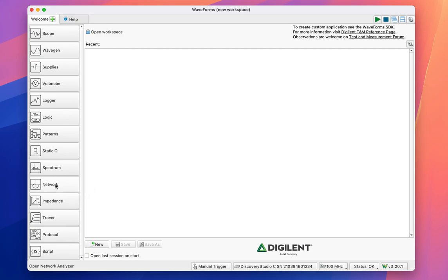with specific values. The ones that I'm using are, for the resistor, 300 ohms, and for the capacitor, 1 nano. So we have our RC circuit, we have our input, which is going to be given by the waveforms automatically using this network analyzer, and the output is going to be taken from the capacitor. So it's exactly the same circuit that we studied on the transfer function.